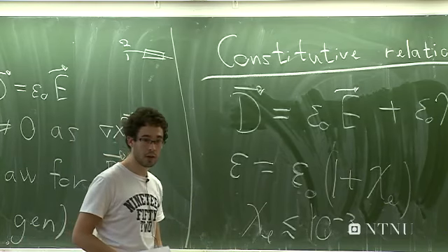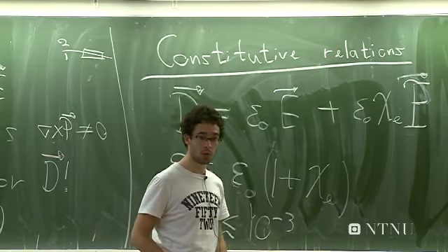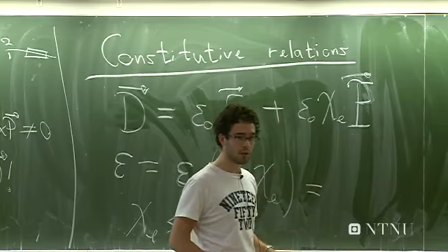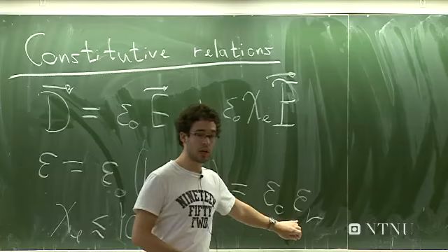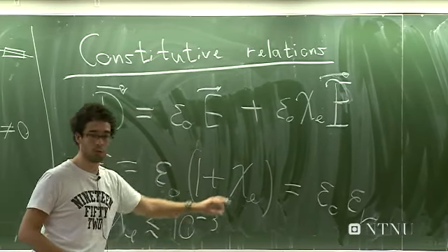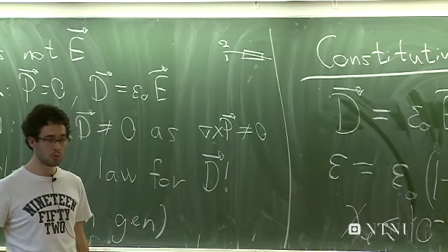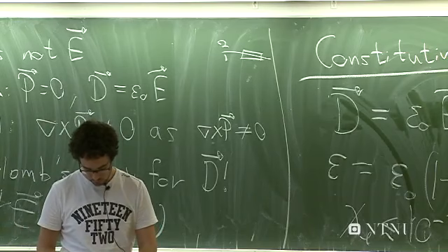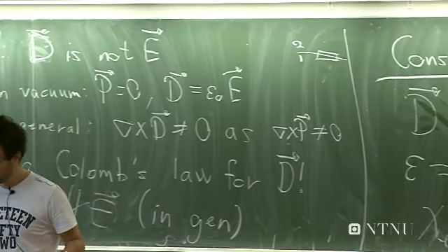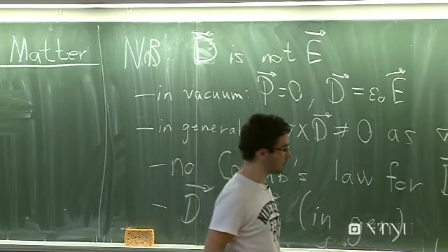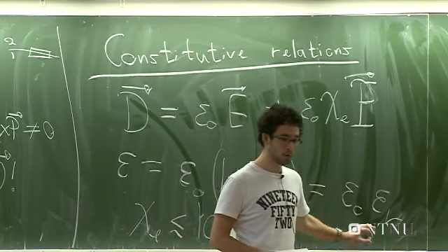While if the material has, let's say, 1.5, then it's more common to give the relative dielectric constant. That's this epsilon r. So then we just quote the whole thing. So you've got to be careful if you're working with these materials to check which one you got. And if you're starting to work with the time-dependent Maxwell equations, then epsilon r is going to depend on the frequency, and then you can't be working in the time domain.